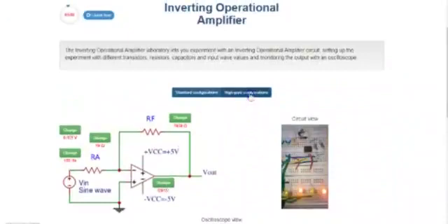In high-gain configurations, it is possible to analyze the performance of the amplifiers up to a gain of 100 volt per volt. Let's start the analysis with Ra of 1 kΩ, Rf of 100 kΩ, voltage of 5 mV and frequency of 100 Hz with UA741 op-amp.